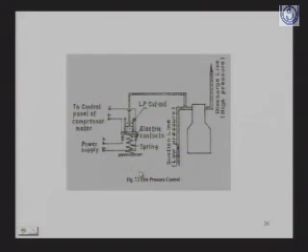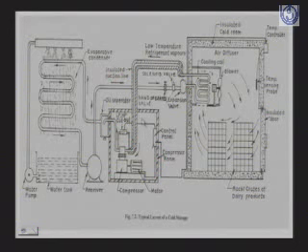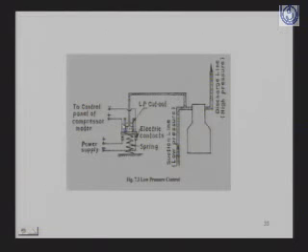You must have seen this in the diagram, that this is the low pressure control, LP, HP cutout are there. Now what are these cutouts? This is the low pressure cutout. Sometimes when the suction is not complete, the pressure is not complete, and if you try to compress, the compressor has to do extra work, and this can spoil the system. So we put a low pressure cutout. This is always kept on the low pressure line, on the suction line.